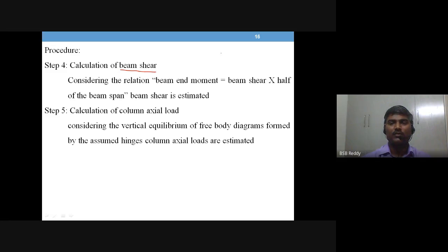Okay, so how do you do it? Let us see. This is a beam where this is B. So you have an anticlockwise moment of 10, right? Let's say the span of the beam is a total of 8 meters. Let's say this is half of the beam, 4 meters, and we are now just taking the free body diagram of half of the part, till the point of contraflexure. This 4 meters is the half of the span of the beam.